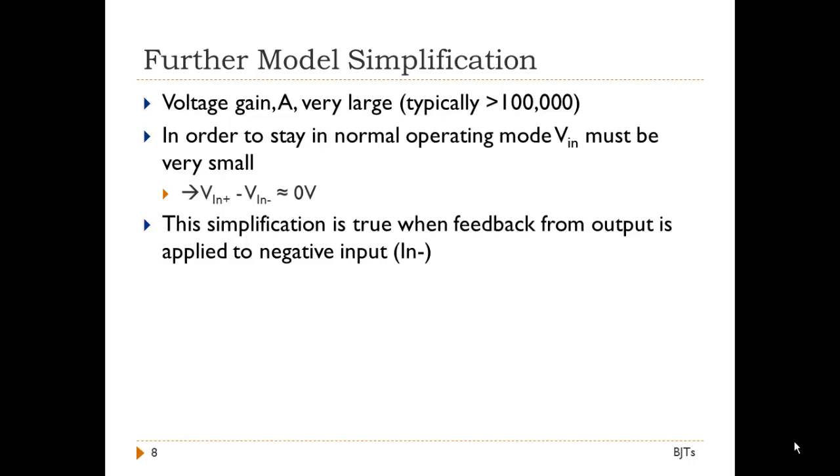As the voltage at Vin plus increases, the output voltage increases. Since the voltage Vin minus is tied indirectly to the voltage Vout, Vin minus increases when Vout increases. Since Vin minus increases, the difference between Vin plus and Vin minus decreases, and so the output voltage stabilizes.